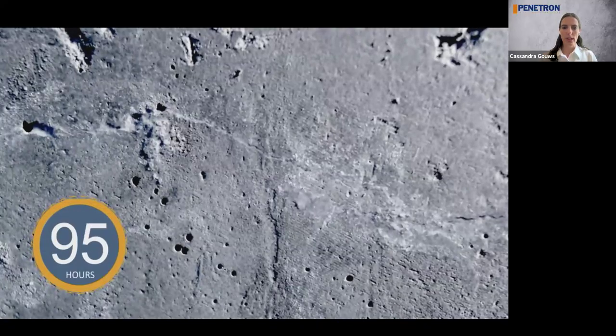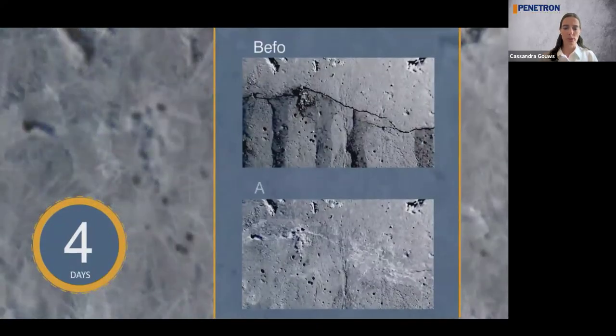Now, take note that in this specific video, it took 4 days for this crack to self-heal itself, but the crystal growth is temperature dependent. So the colder it is, the longer it will take. In very cold winter conditions, it can take 3 to 4 weeks for cracks to self-heal. It's natural. Concrete also hydrates much, much slower in colder weather. So it's all depending on chemistry. But in warmer weather, typically you'll see about 7 to 10 days, and your crack will be self-healed.